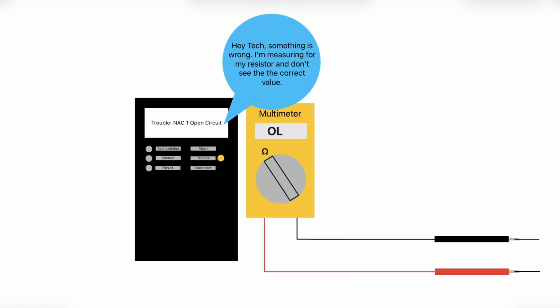In short, the fire panel needs its end-of-line resistor because it uses the measurement of that resistor to determine whether or not the circuit is intact and fully operational. This concept also applies to zones on a security panel.